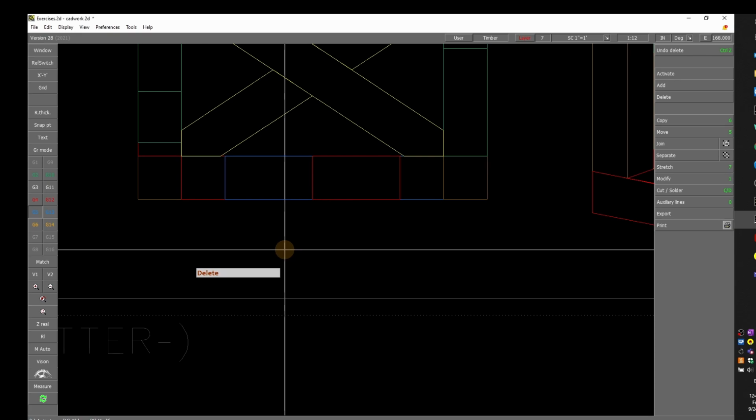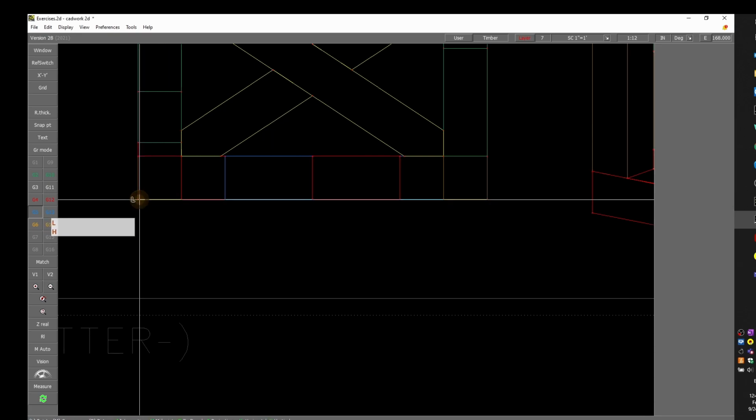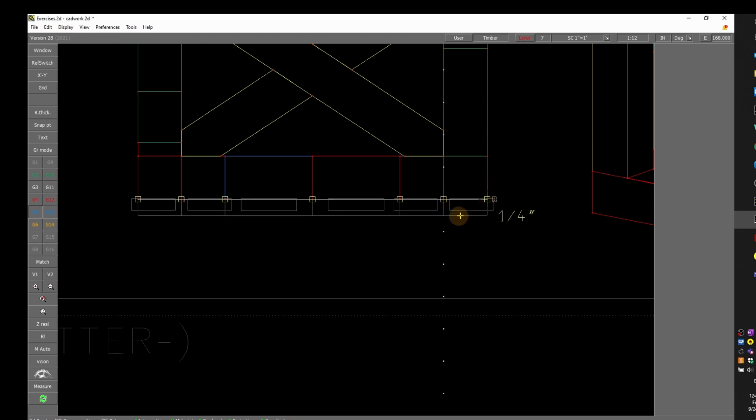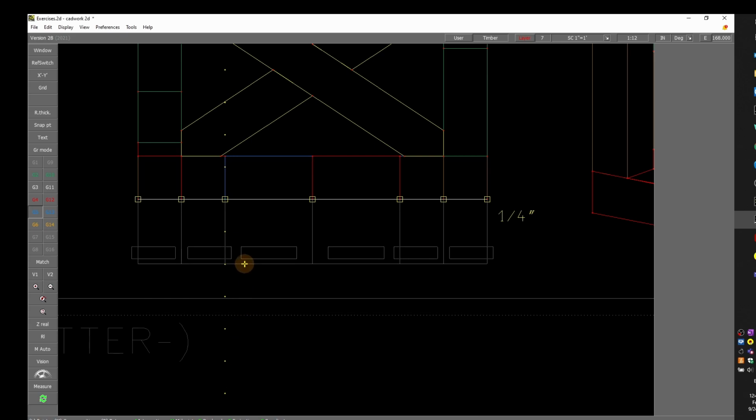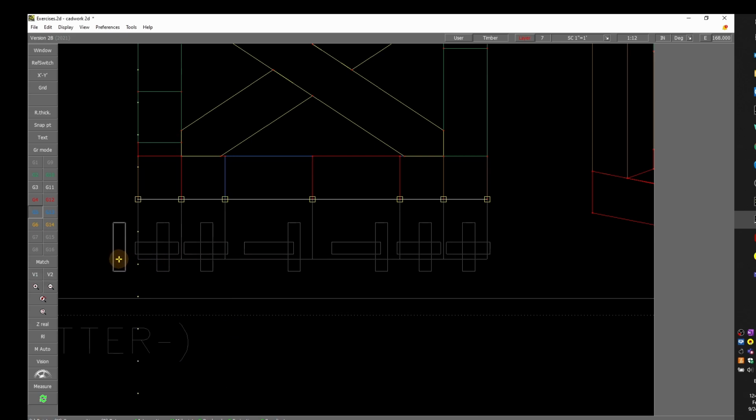Now let me do it again. I'd like to show you a trick. If I press HL and then I pick the 2 points and then right click, here at the very bottom, you can still edit and add more options. So if I'd like to have an added distance, I can press S and you see there is a bold square on the left, which means this is my 0 point for the added distance. But I can also invert, so have the 0 on the right instead. So if you press W, you see that the bold rectangle is moving, toggling left and right.